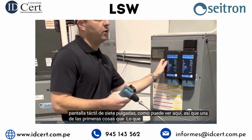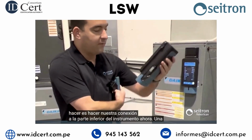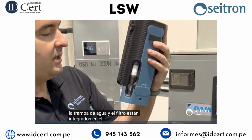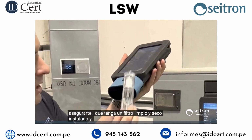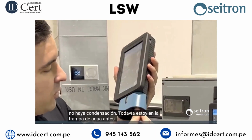So one of the first things that we're going to do is make our connection to the bottom of the instrument. Now, one of the first things to notice is that the water trap, as well as a filter, is built into the instrument. So you want to make sure that you have a clean and dry filter installed, as well as make sure that there's no condensate still in the water trap before you begin your test.